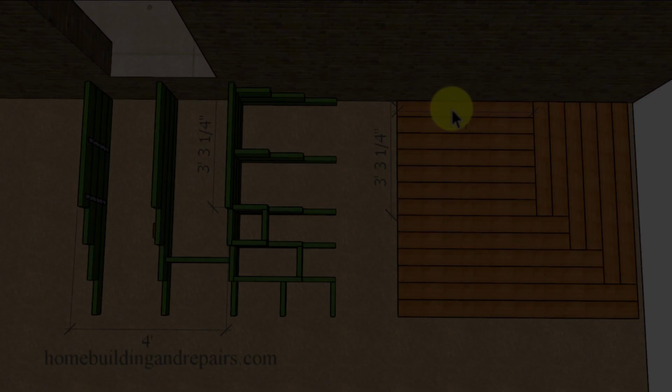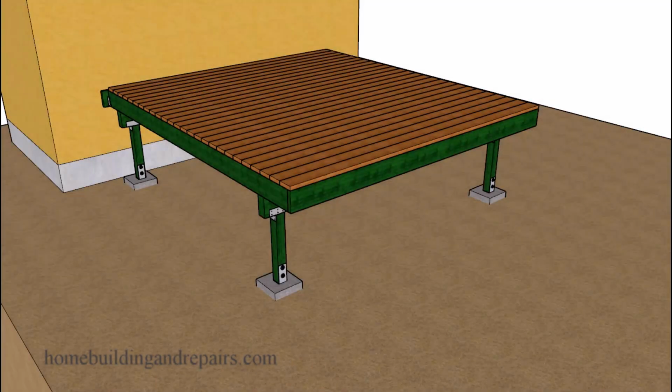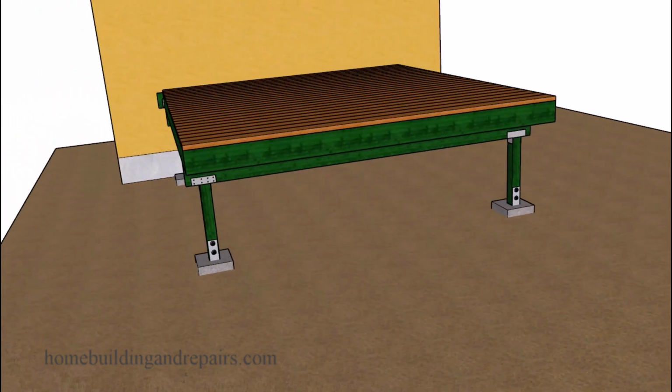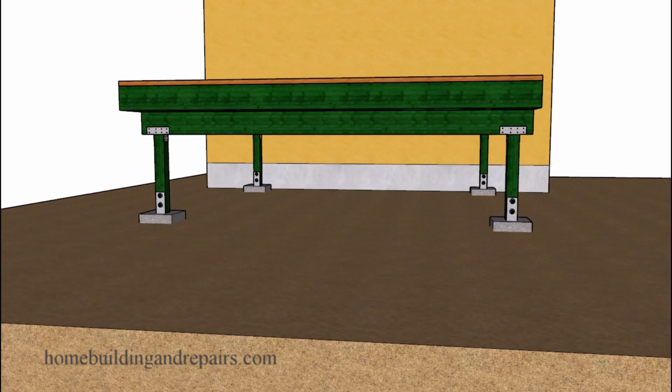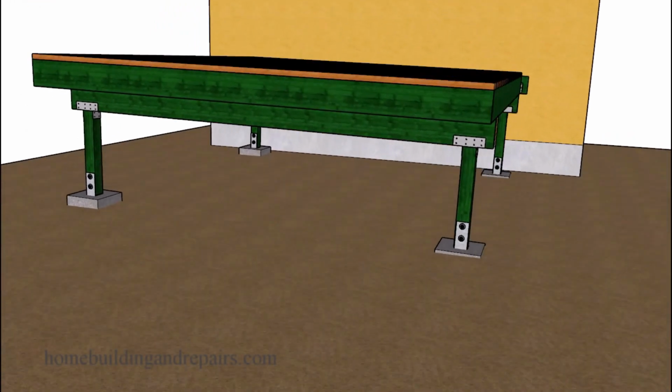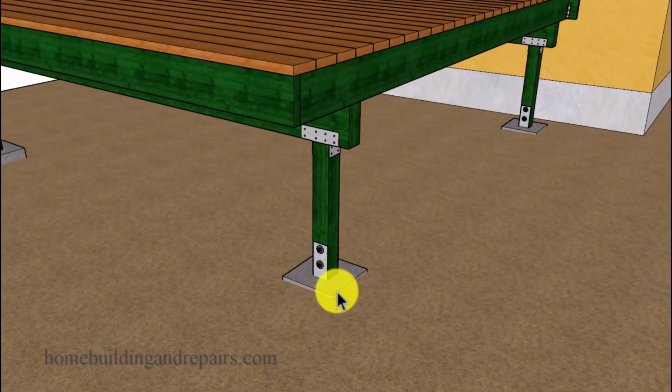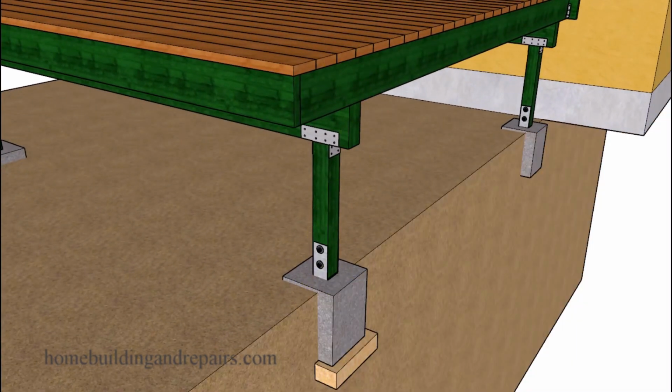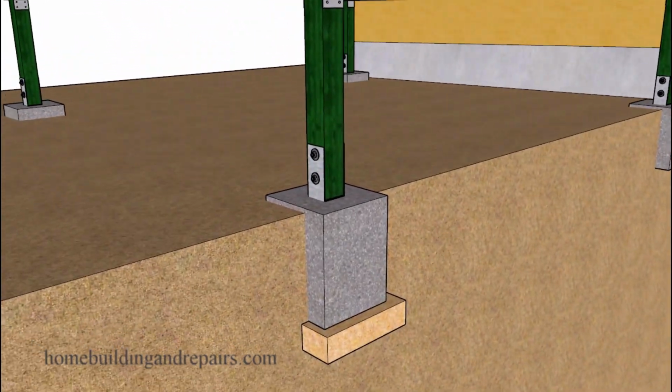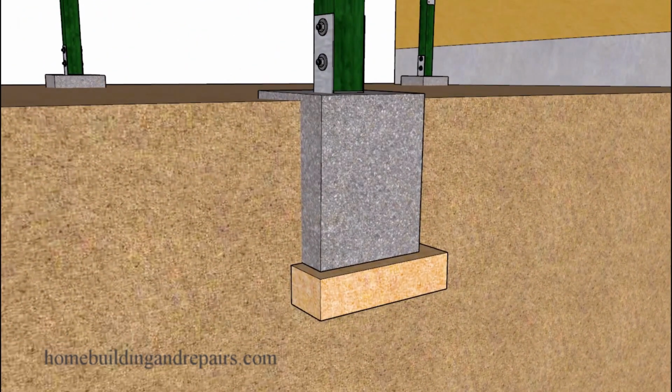In this video, I will provide you with a couple of reasons why your exterior deck might be sinking. And number one on the list is probably going to have something to do with the footing. And from there, we're going to go ahead and suggest that it might have something to do with either soil erosion, that could be from your sprinklers, a leaking water pipe like your hose bib, or even a gutter downspout that's located near the deck footings.